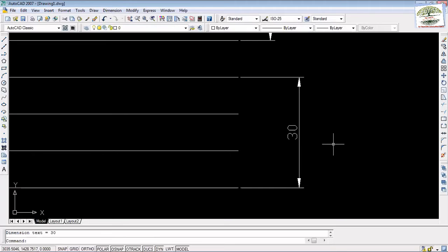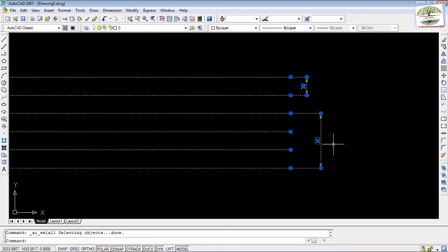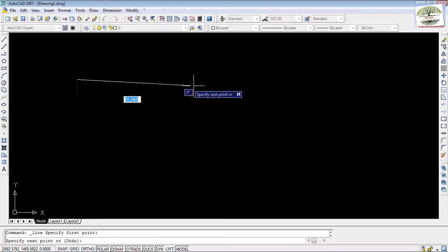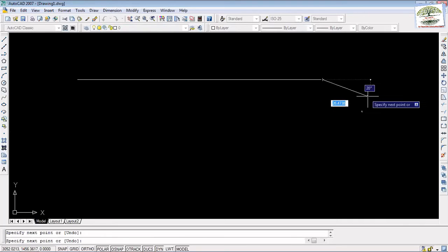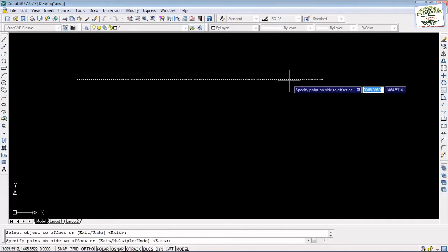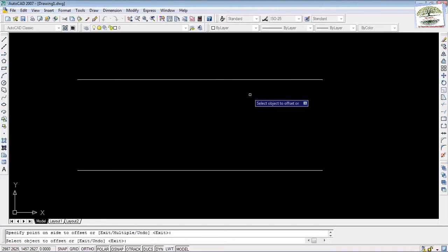So you remember the last class. Okay, we got it. So remove everything, simply draw the line, and better go here with the offset. Click on the offset, click the distance. I am doing around 50. Suppose I'm writing 50, enter. This is the left click on the object.